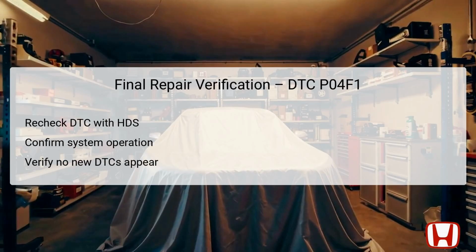After completing the necessary repairs and replacing any faulty components, it is crucial to verify the integrity of the repairs performed. Begin by rechecking for any DTCs using the HDS. Clearing any previously logged codes should also be repeated. Following this, test the overall operation of the EVAP system under various conditions to ensure everything functions correctly.